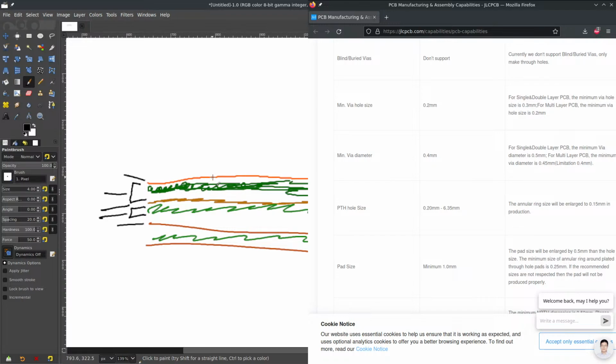So when you have my incredible drawing here of a circuit board, and you have these layers of copper on different levels in between the substrate, and you need to connect them to each other, we use what's called a via, or a vertical interconnect. A via has what's called the annular ring, which is a bit of copper on the outside here, and then a piece that goes through to the other side, that's the through hole diameter, and goes to the annular ring, and this makes a conductive path between them. They're these little things, and if you look at any circuit board, pretty much you'll be able to see them.